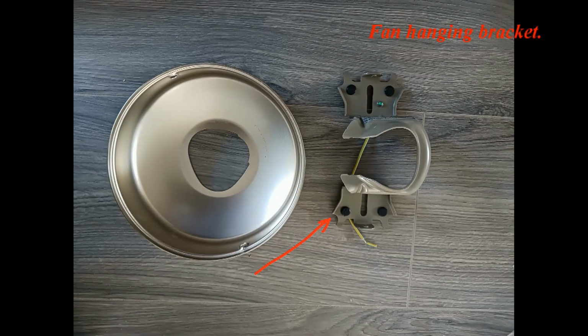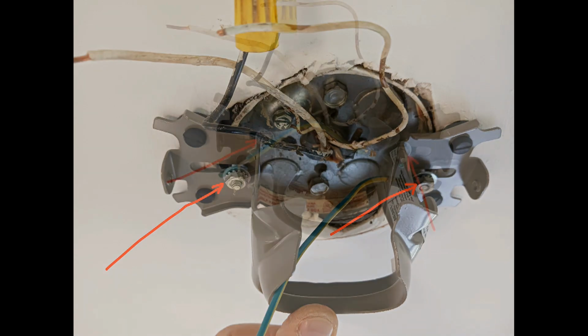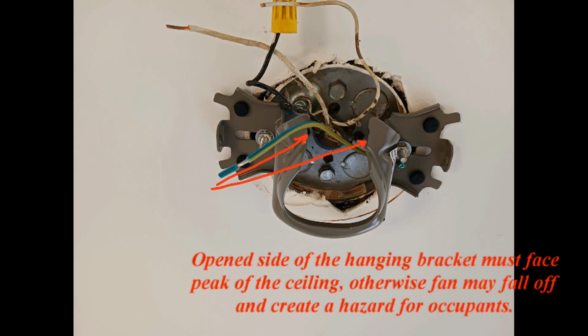Fan hanging bracket. Attach fan hanging bracket to the fan-rated junction box. Tighten the screws. Open side of the hanging bracket must face peak of the ceiling, otherwise fan may fall off and create a hazard for occupants.